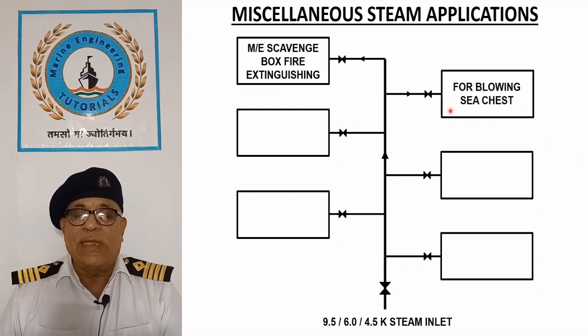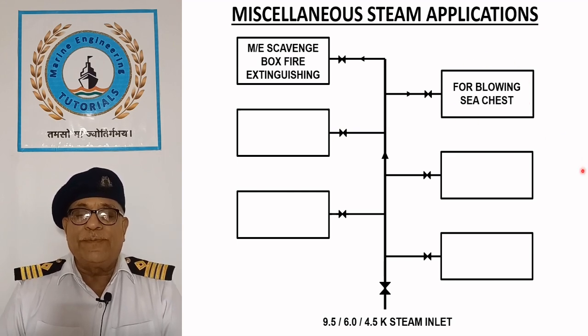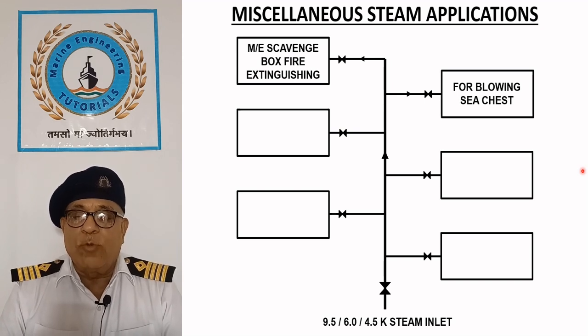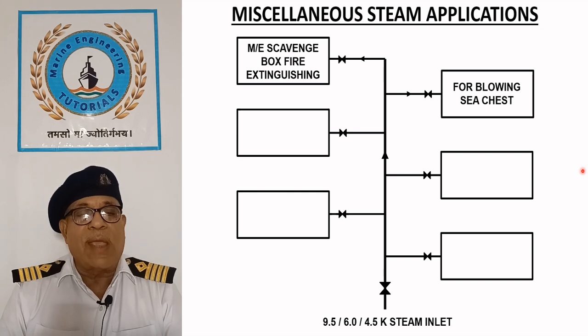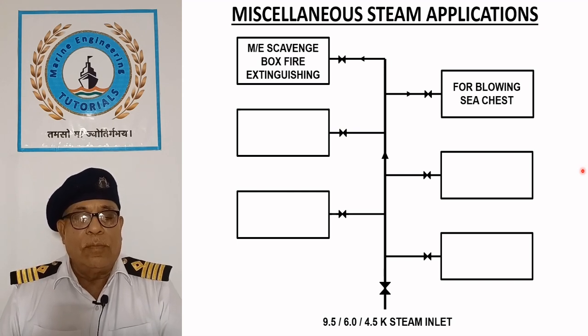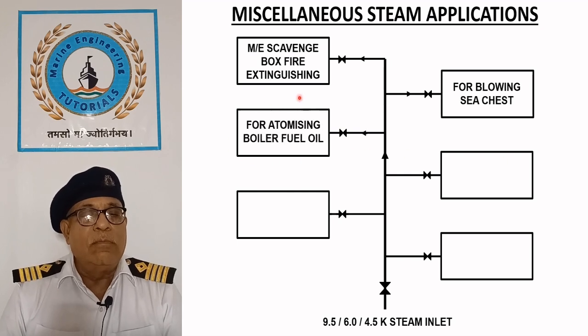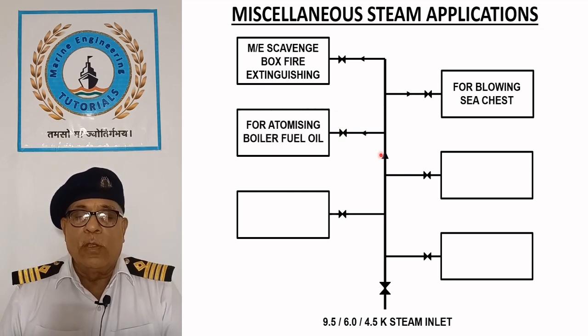For blowing sea chest. The ship's sea chest is occasionally fitted with a steam blowing connection to clear gratings or melt ice. For atomizing boiler fuel oil. Steam jet burners used in large boilers utilize steam for atomizing fuel oil.